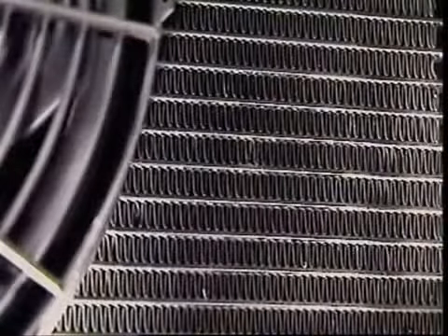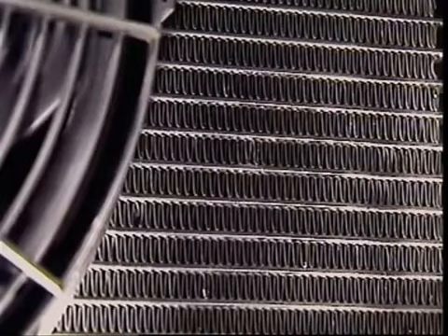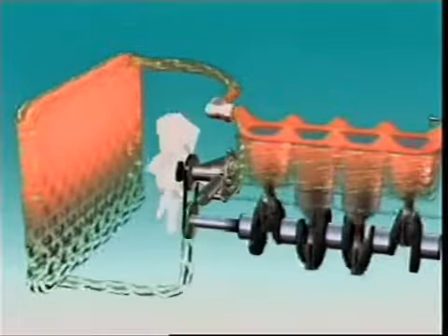In the core, small, thin cooling fins are in contact with the tubes. The shape of the fins increases the surface area exposed to the air. Where coolant touches tube walls and where the tubes touch the fins, heat is removed from the coolant by conduction, then by radiation and convection at the surface of the fins. Air rushing by carries the heat away. Liquid emerges cooler at the bottom of the radiator. It travels through the lower radiator hose to the water pump inlet, then through the engine again.